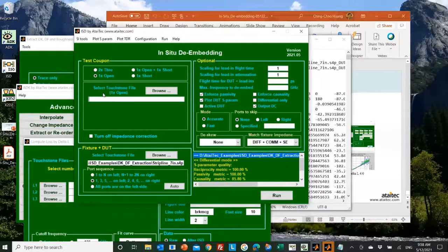What we found is that the current integration on the VNA only allows you, when you're performing a 1x open, to measure it from one port, and the assumption is that by measuring the 1x open of, let's say, your P leg, you can reuse it on your N leg when you're doing the de-embedding, just because the tool is looking for the reference plane. It doesn't really matter if you choose the P or the N.